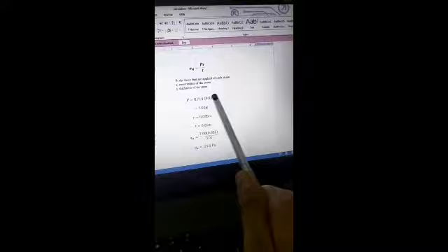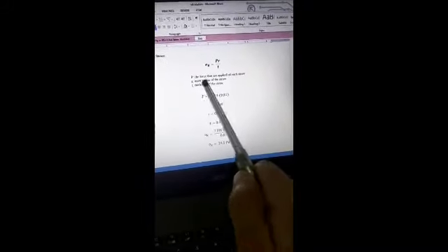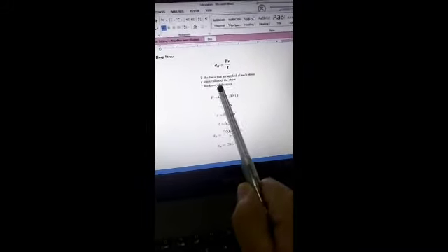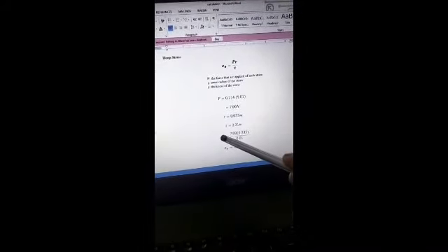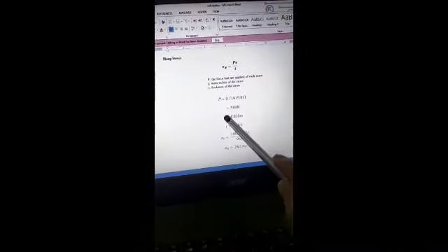Alright, for the hoop stress, this is the formula, and P is force that applied on the straw, R is the radius in the straw, and T is thickness of the straw. Okay, for the inner radius for the straw, we have counted as 0.035, and the thickness of the straw is 0.05.